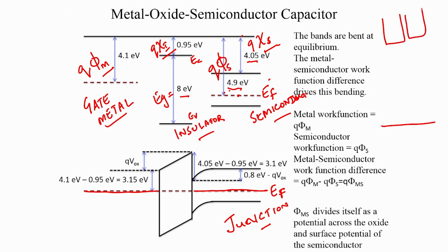So, you have these 2 buckets and you have less water here and more water here, and this corresponds to a Fermi level that was higher or work function that was lower, whereas this corresponds to a work function that is higher, and when you merge these 2 buckets, the water flows from there to here, thereby aligning the Fermi levels. Okay, so we looked at all these analogies and we had a mathematical derivation of why the Fermi levels should align at thermal equilibrium, because the flux of the carriers have to be balanced.